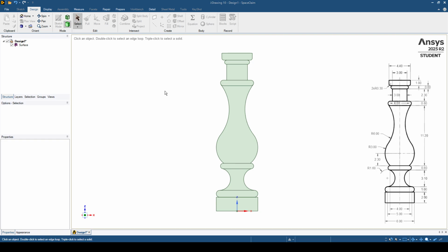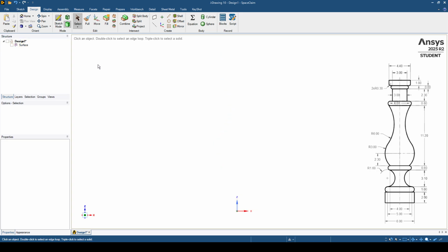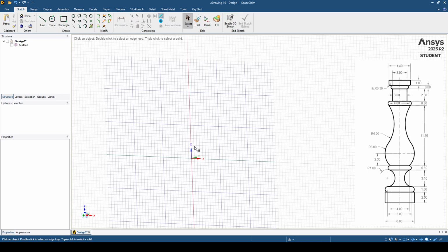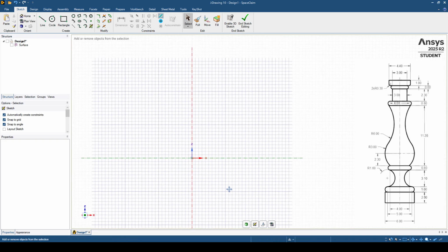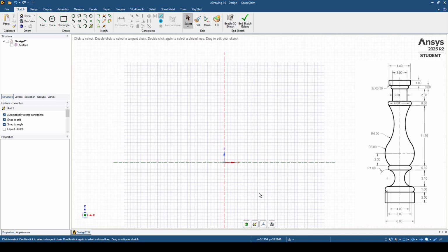So first of all, I'm going to hide this 2D surface and start the drawing together. I'm going to choose sketch. I'm going to choose the y-axis in my case here, and directly I will click on the plan view, as you can see. So I'm going to start from the bottom, and in order to do this, I'm actually going to choose the rectangle and draw it with the define rectangle from the center and start from the origin.